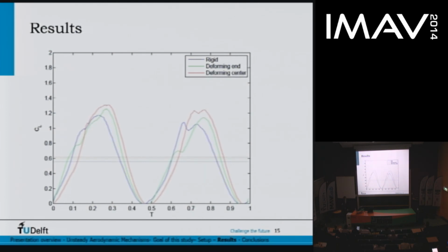If this is your symmetry plane, the wing will move without any deformation like this, but if we add deformation, it will first move like this, and then. So if that's not timed perfectly, then you will get a bit of negative lift due to the deformation not being in sync with the actual motion of the flapping. Is that clear? Okay.